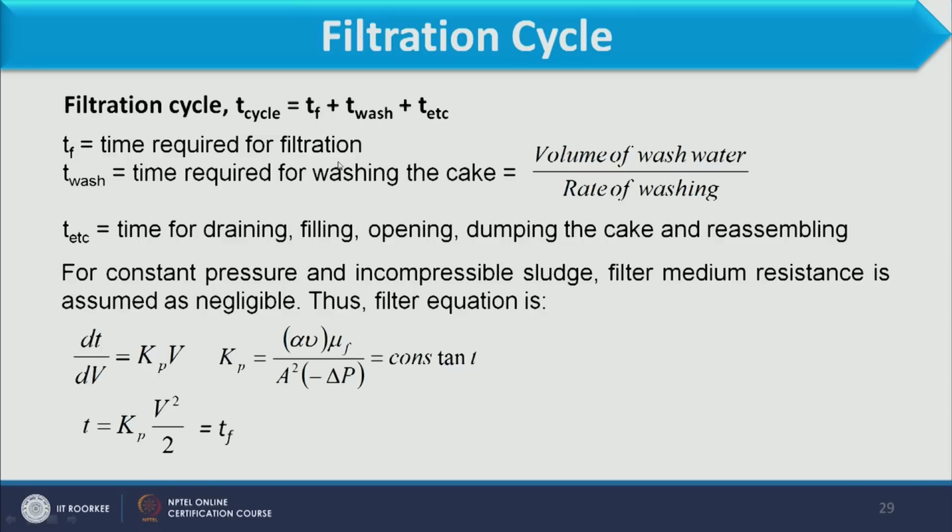Tf is the time required for filtration, T wash is the time required for washing the cake, which can be defined as volume of wash water divided by rate of washing, and T etc. is the time for draining, filling, opening, dumping the cake and reassembling.